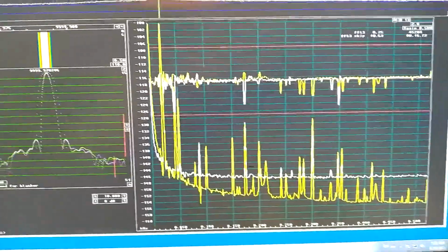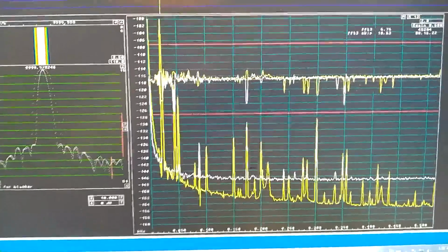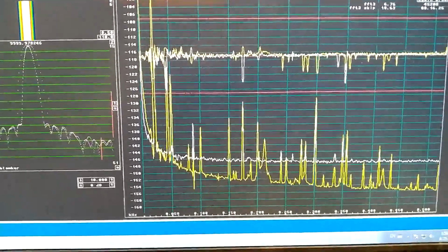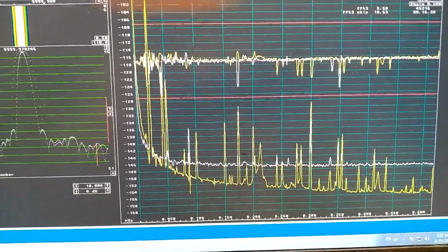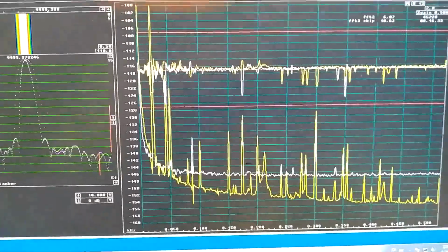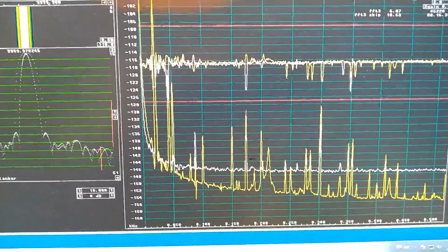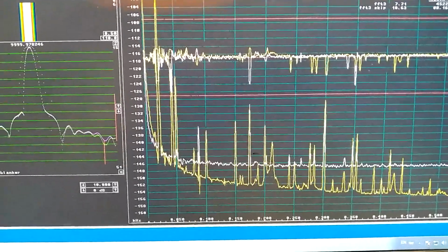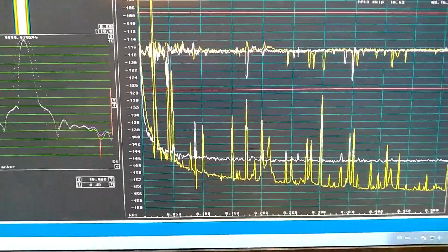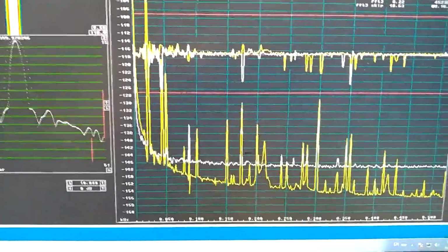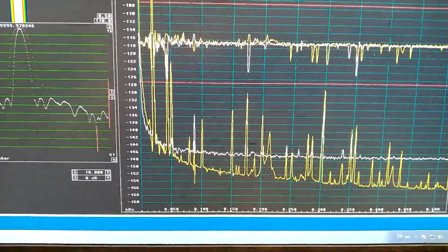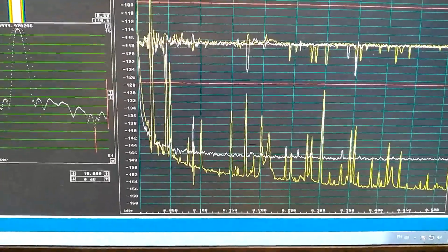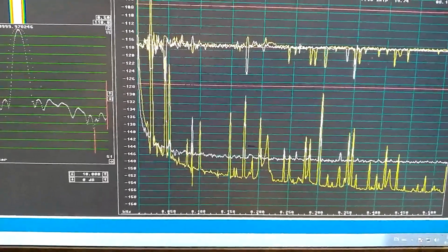So this made a difference. It's interesting, I think, but I don't think it's something that people will use, because it is good enough already just by removing the C14 capacitor for typical purposes, like people wanting to work on 122 gigahertz. This is a good reference oscillator with the capacitor removed.